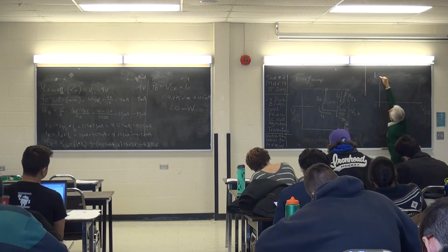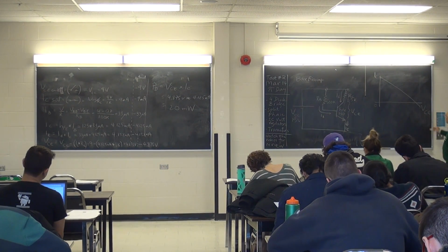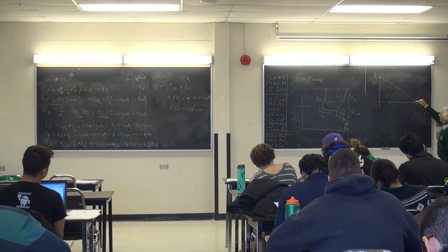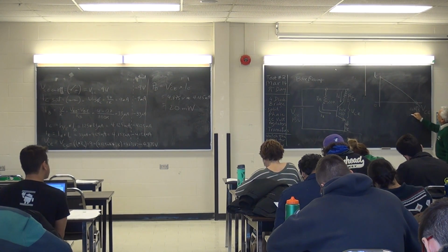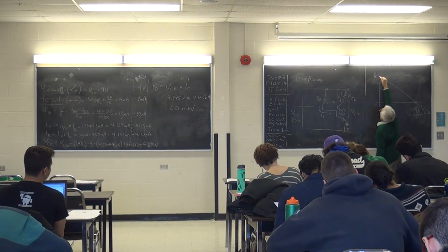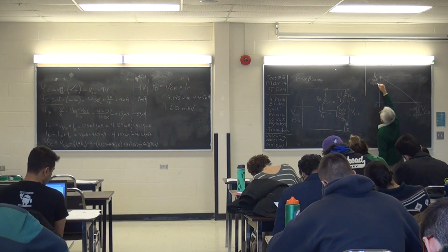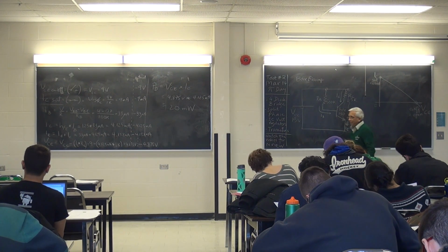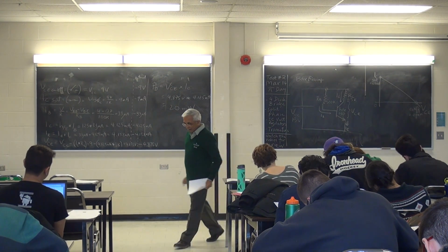Draw a line. This point, cutoff. Open. This point, saturation. Closed. First thing I do is identify cutoff and saturation.